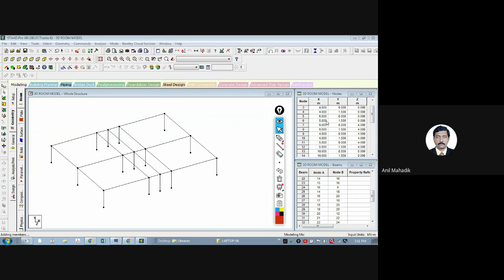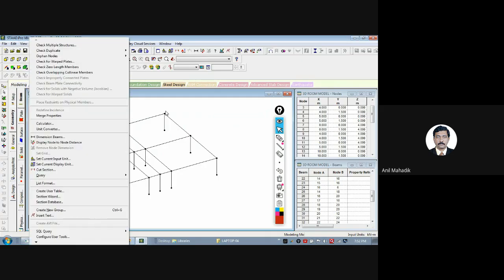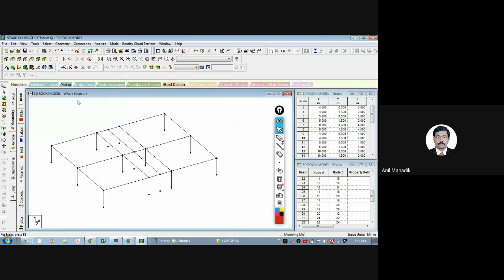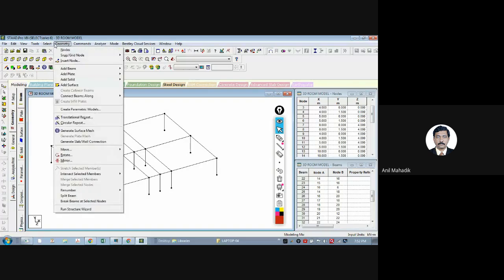Hello sir. Yes. When we mirror, at the plane from which we mirror, double points do not come there, double nodes do not. And if I see, he's asking whether there will be duplication of the nodes or members. So whenever we run the model before the analysis, we check for that. There is a command, I will tell you before analysis, that we can use to check duplicate nodes. I'll tell you again here also. So how to check whether there is any duplicate node or duplicate members?